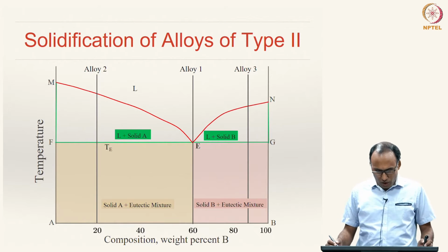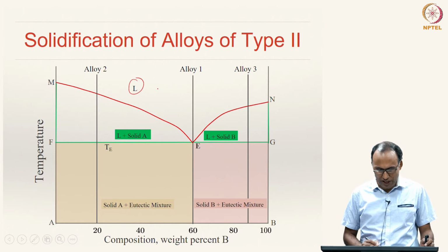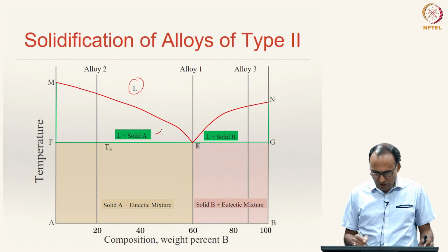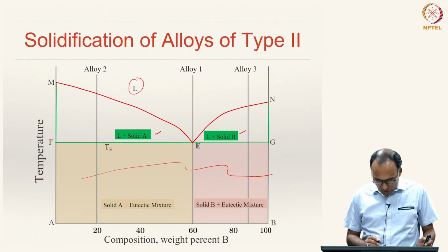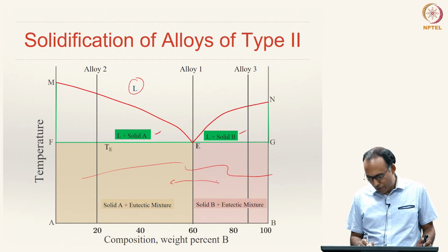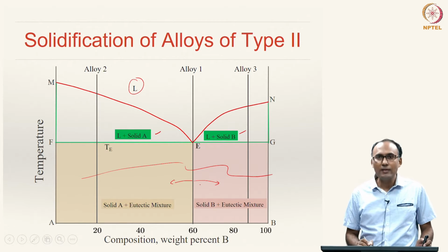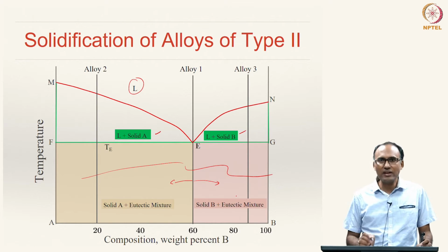All right. So, as we have already mentioned, above the solidus liquidus line you have everything as liquid solution of A and B, and you have 2 phase regions, that is liquid plus solid A and liquid plus solid B. This entire region is solid A plus solid B. Here we are showing the hypoeutectic alloy region and the hypereutectic alloy region. Left of the eutectic composition is hypoeutectic, right of the eutectic composition is hypereutectic, both are 2 phase regions. However, there is a slight difference